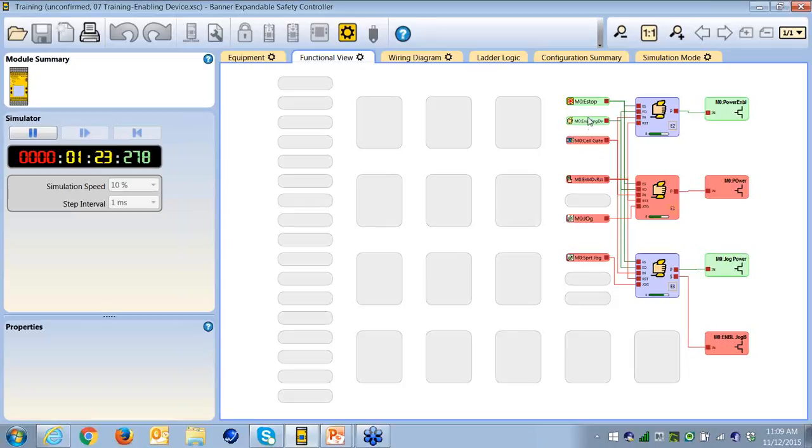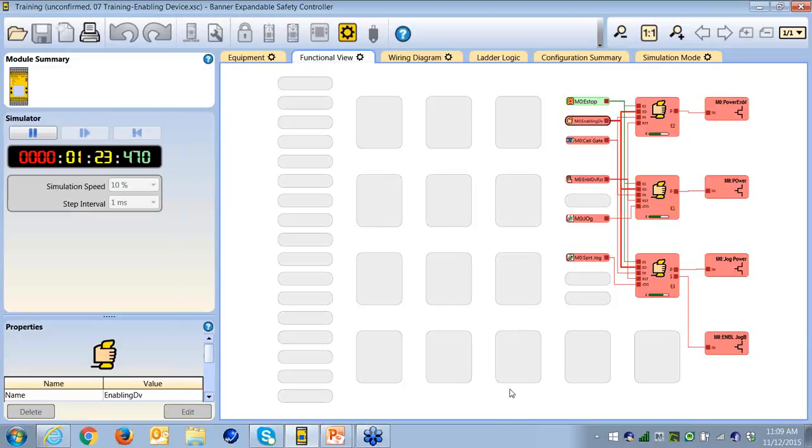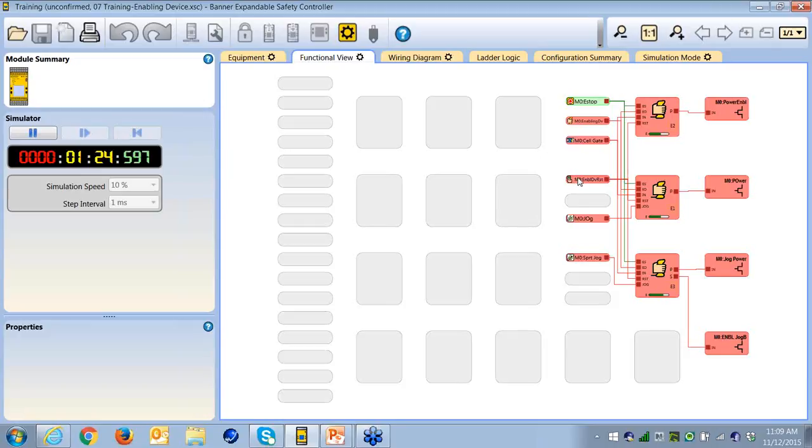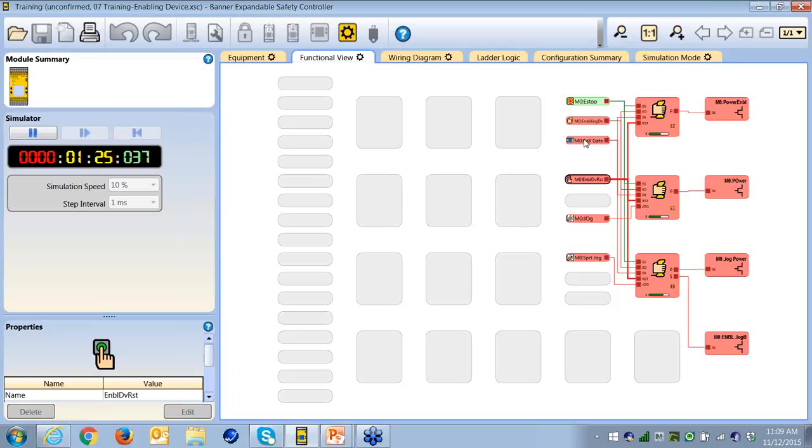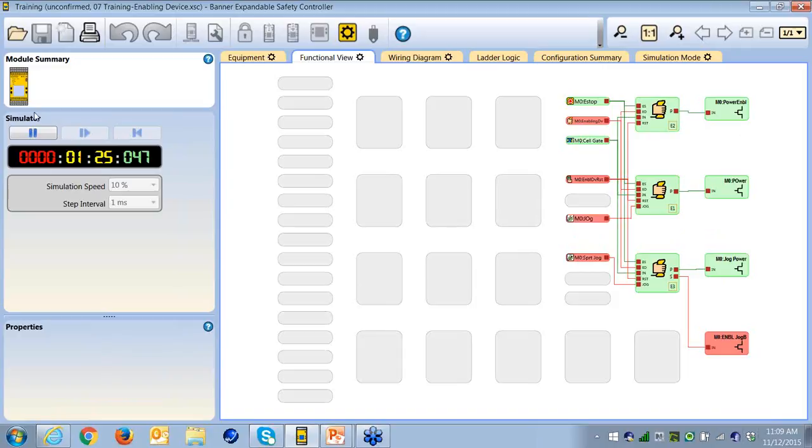We'll assume that we're done with this now and we want to go back to normal mode. If we just now have the gate closed, nothing will happen. And the reason is we have not done a reset, which says, yes, we are indeed ready to go to that. And now if everything works right, our 3 outputs go high. The jog buttons, while I can turn them on and off, obviously do not perform any further function.